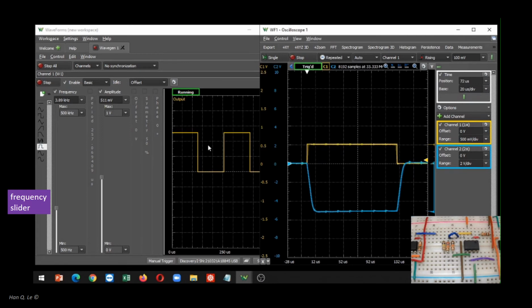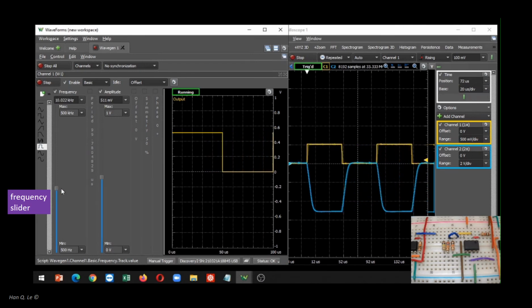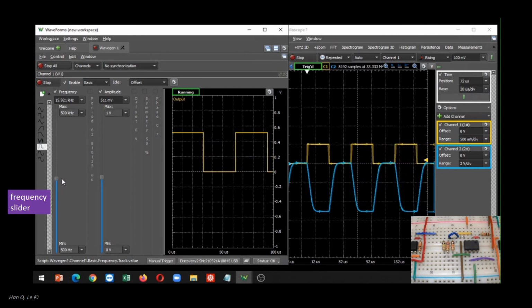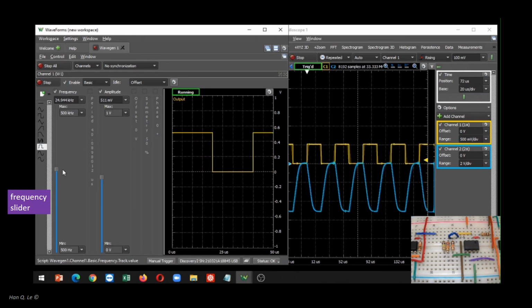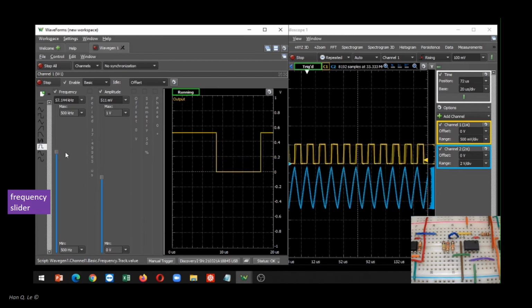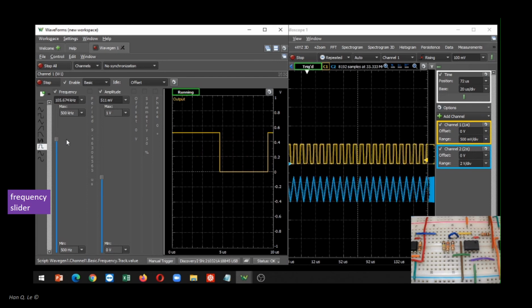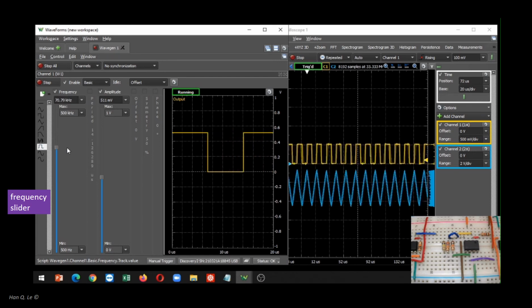This is a demonstration of the process. As the frequency increases, the rising edge and falling edge come closer to each other. At some point, the output cannot fully reach its maximum and minimum in one cycle, resulting in smaller modulation output, the same effect of decreasing gain at higher frequency in A5. The 3 dB bandwidth of the square wave in this demonstration is practically the same as that of sinusoidal wave in A5.